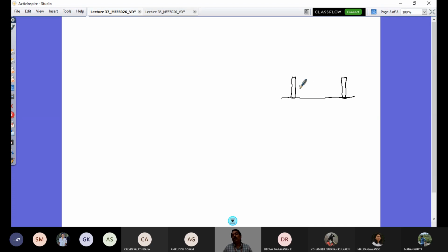And I'm going to draw this simple schematic representation of my vehicle, considering equivalent springs, all four springs of the vehicle into two single equivalent springs. And this is the separation distance of the spring, say S. Some of the time the rear axle will be a solid axle, the front axle will be with the independent suspension system.